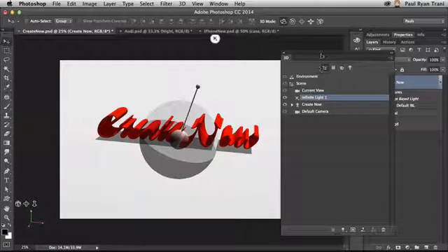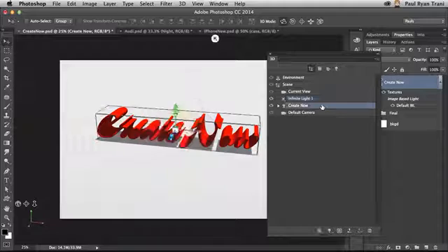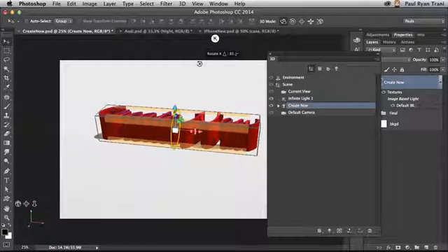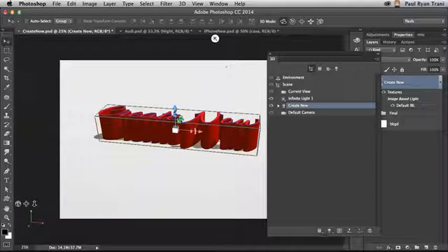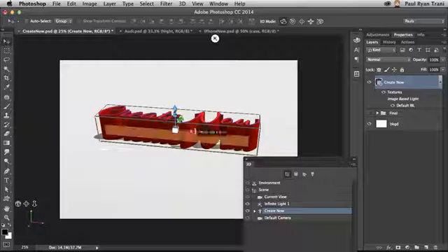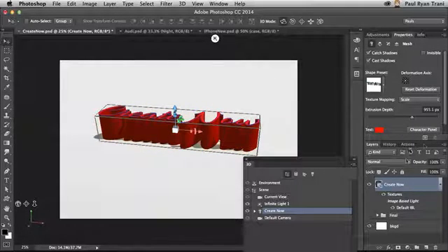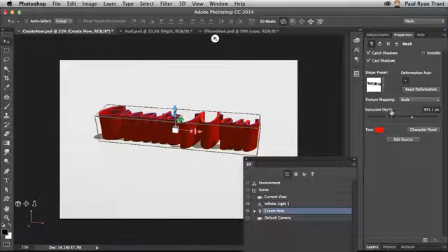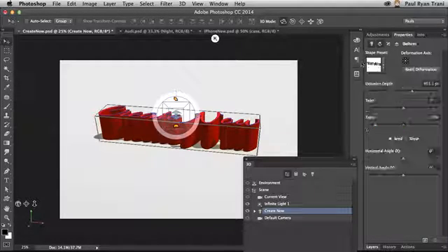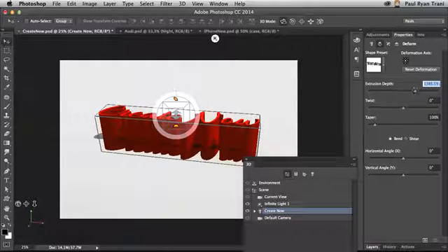Now, I can even manipulate the text that way as well. So look, as I roll over, oh, I can have it stand up so it's facing upward like that. So maybe you want even more control over the position of this text. Go into the Properties panel. In fact, right over here, you can see the extrusion depth. In fact, more control over the extrusion. So I can extrude it out like that. I can twist it. I can taper it.